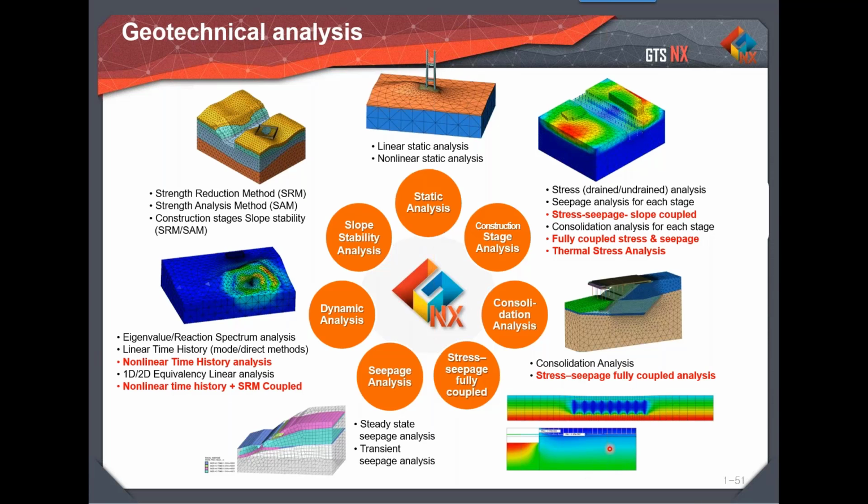So this will be very helpful because in real time, what happens is as the deformation is happening, the permeability of the soil at that condition is actually changing in real time. So as the deformation changes, the permeability changes. And again, as the permeability changes, the deformation variation takes place. So it's a time dependent analysis. So you can get the real time, I won't say real time, I would say the real time approximation easily captured using the coupled analysis. Then you can do a consolidation analysis, as I already explained. And all these analyses that I have explained till now can be done in construction stages as well.